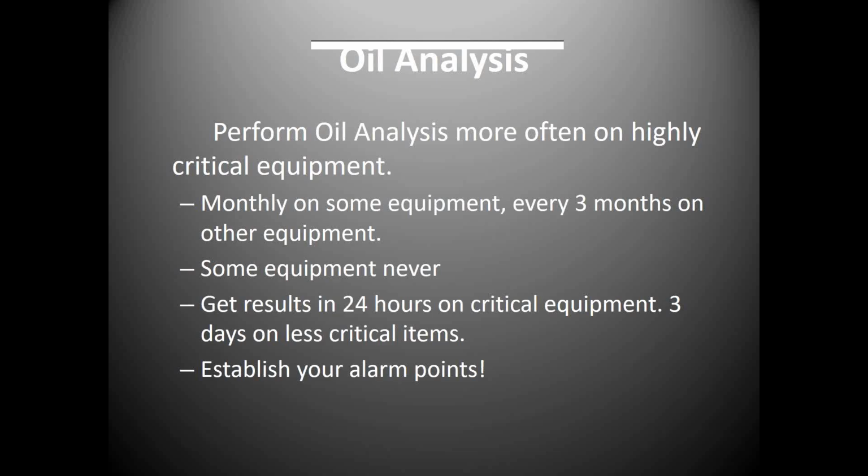We want to know right away what's happened. We don't want to know 3 weeks from now what our oil analysis results were. And make sure you establish some alarm points. What are you looking for? What are the particle counts? And how low can my additives get before I actually react?